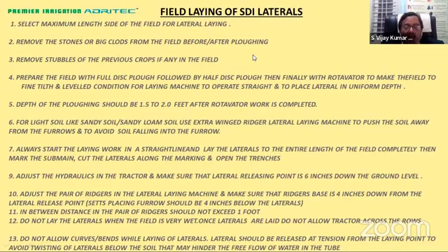Do not lay the laterals when the field is very wet, because the tractor is going to totally disturb the whole thing. And also, once the field is laid out, do not allow the tractor to go in the opposite direction across the rows.